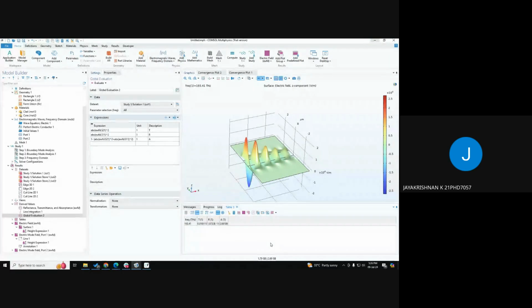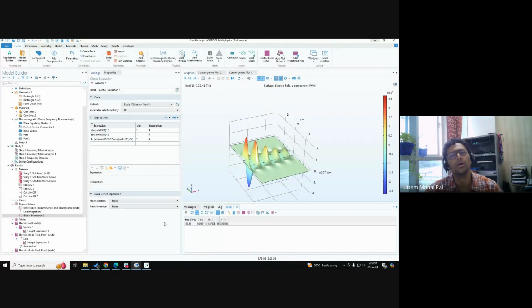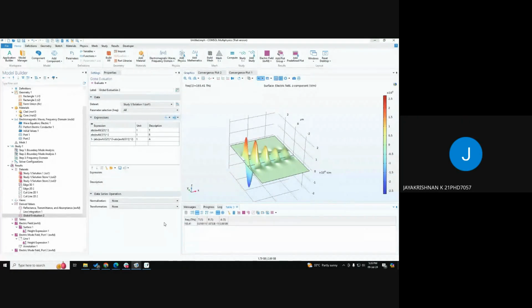So I was trying to solve a paper on a PCA photonic crystal fiber. The graph is loss versus wavelength. When I was trying to solve it in COMSOL, I have to manually extrapolate the effective index values for each and every mode, then take the imaginary part of the effective index and input it to an equation to calculate the loss. Is there any other way, like calculating the S parameter, for calculating loss? No, that is the only way.